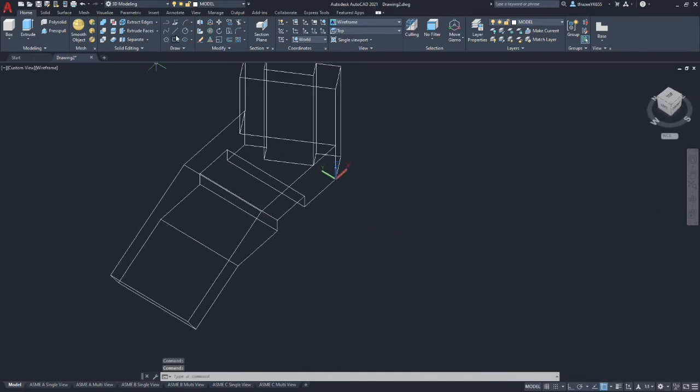We're going to create a line. It's going to go from this intersection, and we want ortho on at this point. And we'll just go past the part. And then we need another construction line to go from this same point all the way out another axis. And we'll offset those two lines to find the center of the hole.